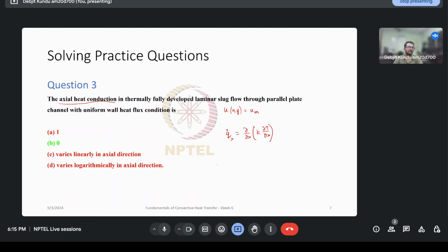And when the heat flux through the wall is constant, we can write this ∂T/∂x as simply dT_m/dx, where that is the bulk mean temperature, as a function of x, is simply equal to q_wall, that is the heat flux from the wall, times the perimeter, divided by m dot, that is the mass flow rate, times C_p, that is the specific heat.